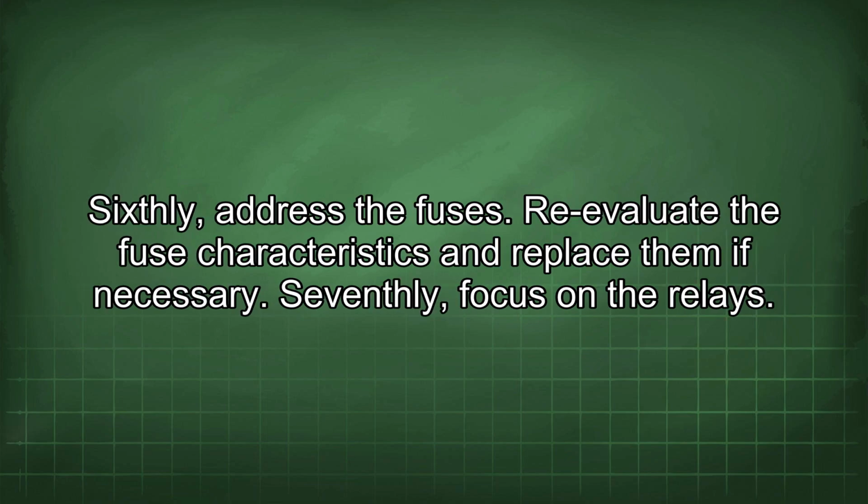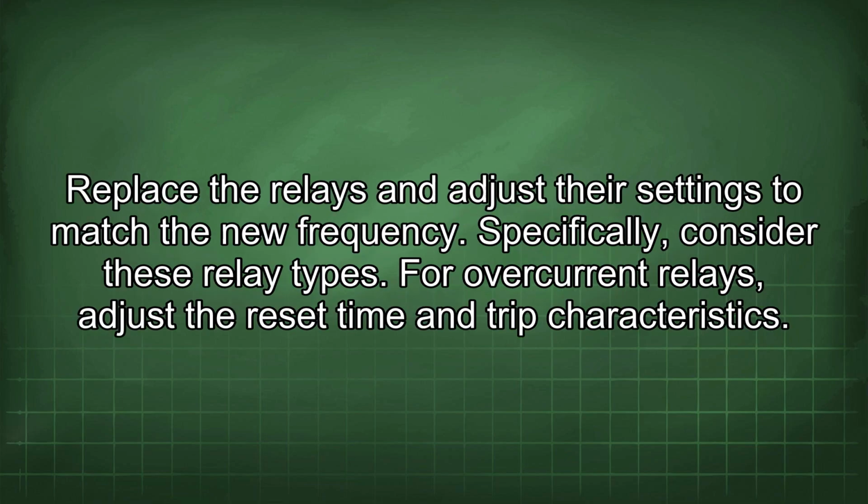Sixthly, address the fuses. Re-evaluate the fuse characteristics and replace them, if necessary. Seventhly, focus on the relays. Replace the relays and adjust their settings to match the new frequency. Specifically, consider these relay types.